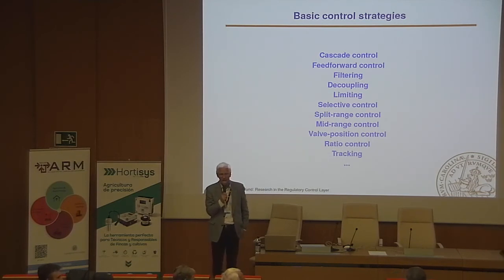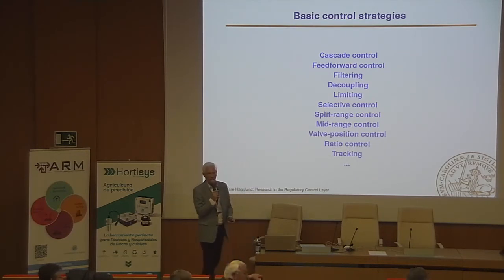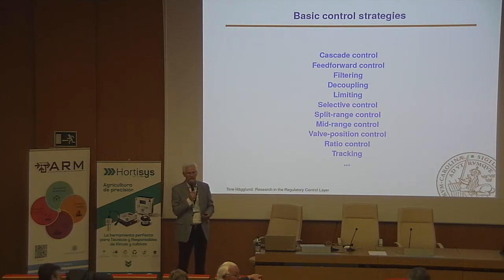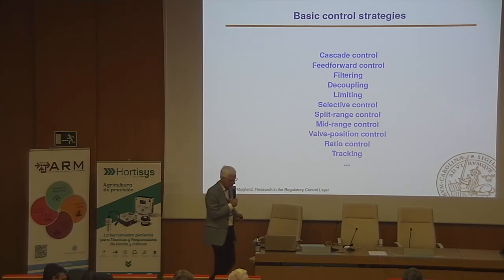Okay, and what's your opinion about people who say that the advanced control level gives us a common framework to substitute a lot of ad hoc strategies for specific units? I mean, the low-level controls and single loops stay, but you would eliminate or erase all these ad hoc strategies like cascade, feed-forward, and selective, and put an MPC, for example, that gives a common framework to control a lot of units or different processes in a multivariable way. Yeah, it is a common framework.